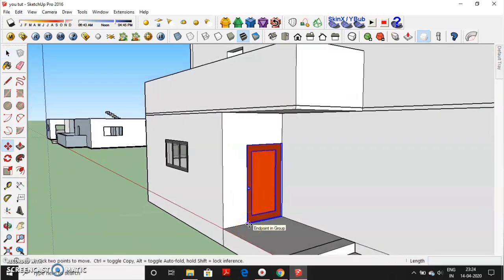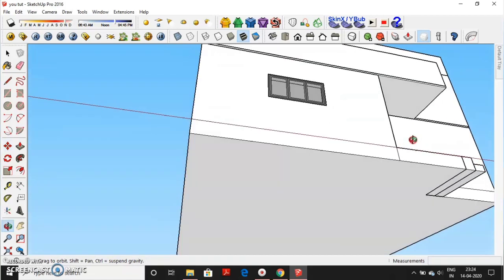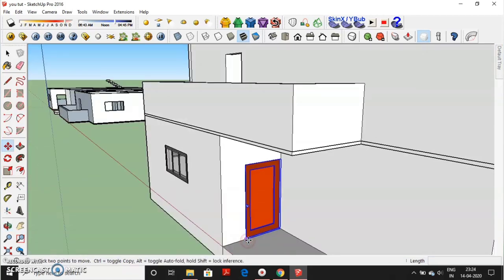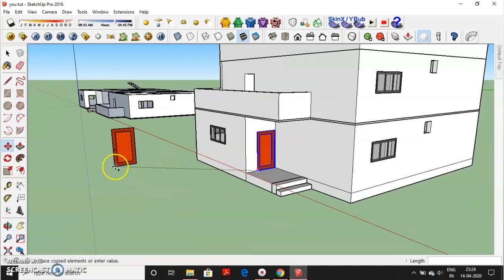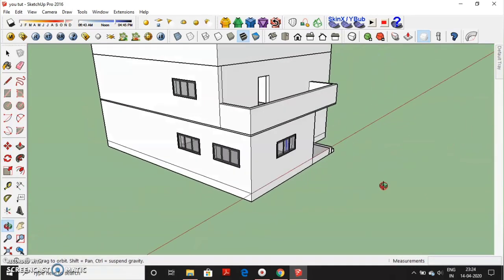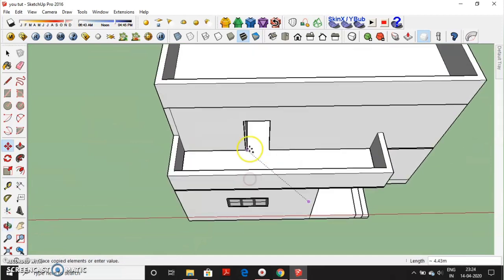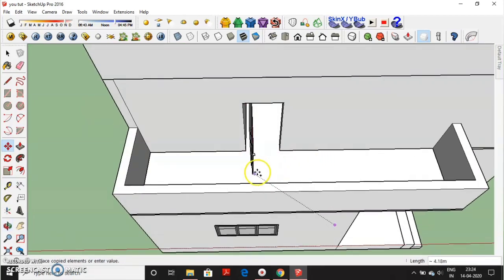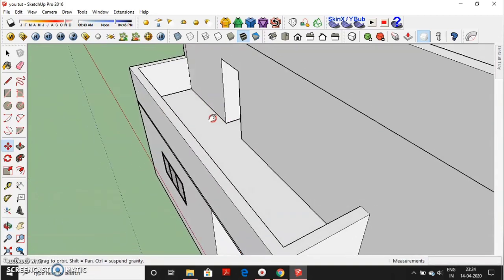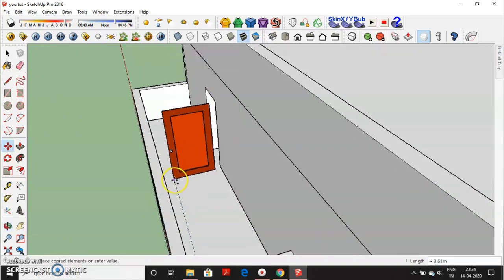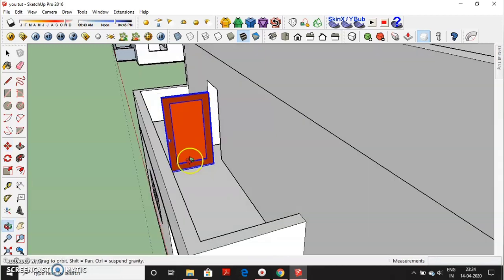This is one piece of advice. Whenever you make a group of an object, in a complex object, always copy it once somewhere else, so that not every time you need to copy it, or if by mistake unnecessary objects have come into the group, you can just explode the group and delete it.